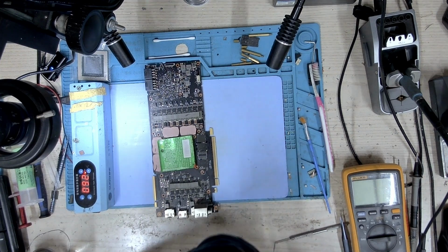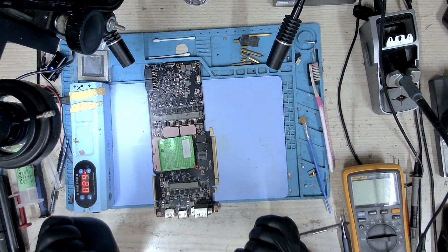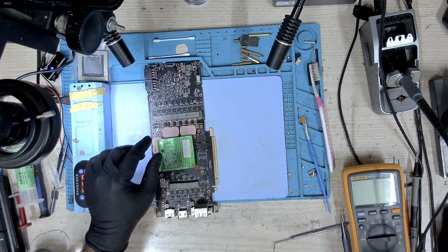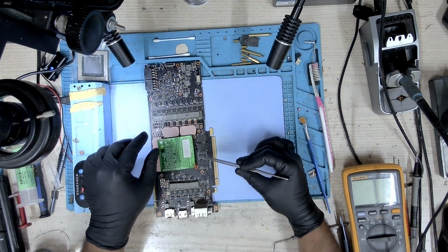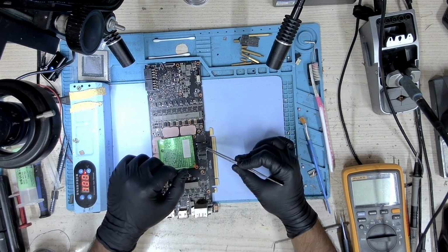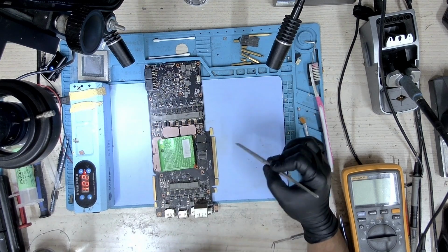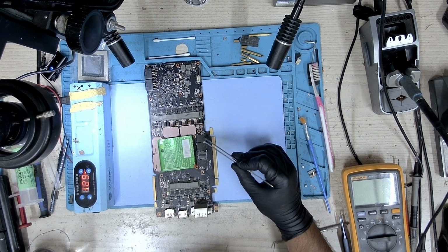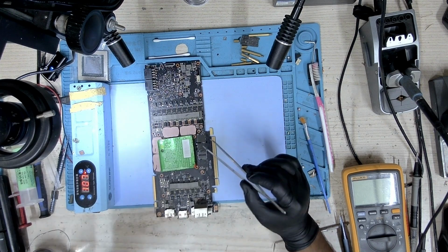Okay, so I have gone ahead and put the card on the bench. Let me show you. Now, A1, A0, B1. This time we got error on B1. My preheater is already on. It's heating up the board. We have already replaced the chip that is B0. This time we are going to replace it with B1.